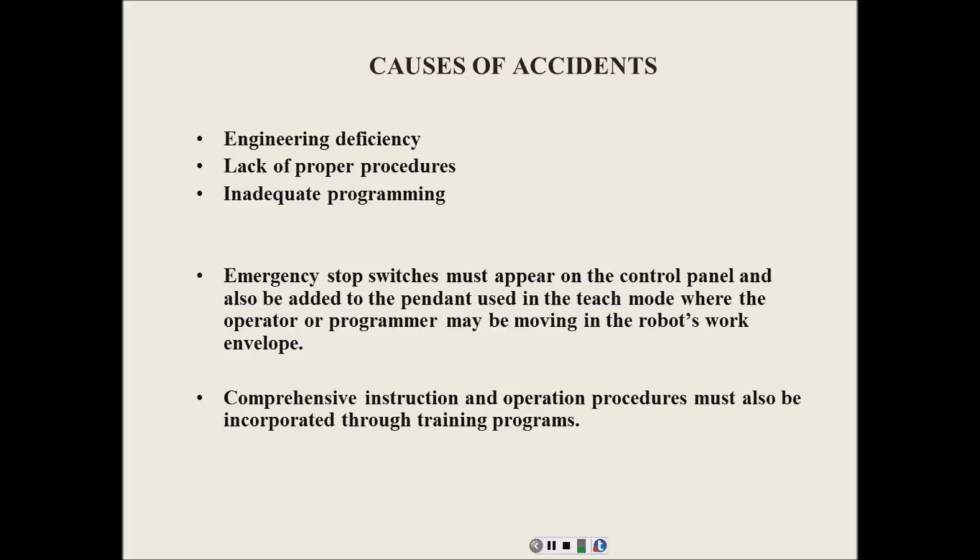And then everybody in the work cell should have a teach pendant. It's real hard for most people to get into our work area, but it's also hard to get into our work area with the teach pendant. So, y'all doing things, remember the person that is controlling the teach pendant is controlling the work cell safety.